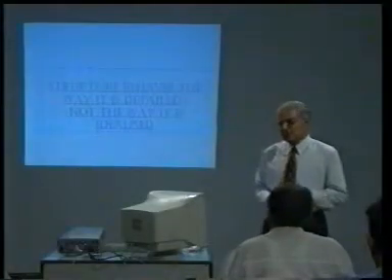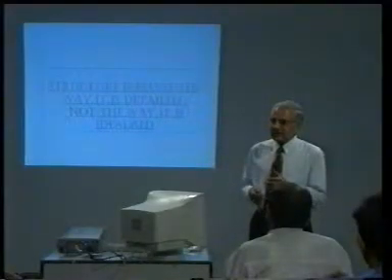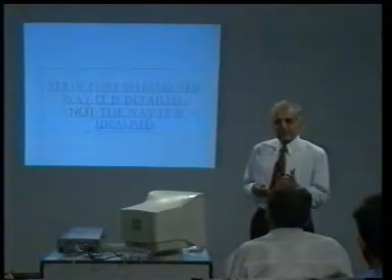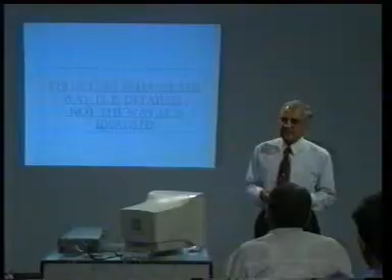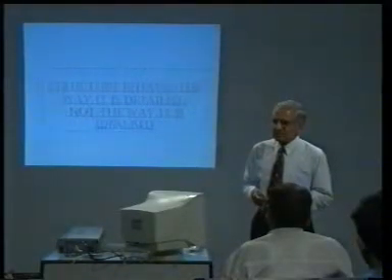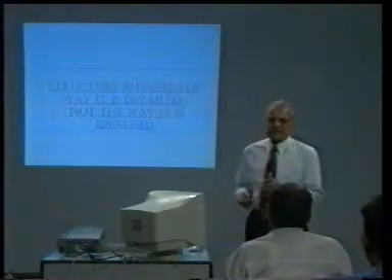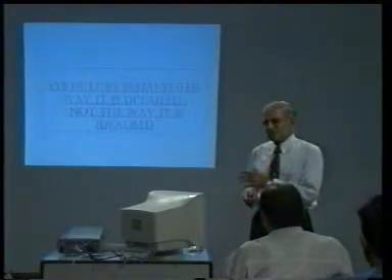Now, before we go on to discuss each of those aspects that I have just listed, we must understand that the structure behaves the way it is detailed and not the way it is idealized. You may plan to have a simply supported condition at the support, but you may actually be providing the reinforcement of the column and the beam to go into each other. This condition actually will be a fixed condition and not a simply supported condition. So, these aspects I shall explain as I go by, but this is a very important aspect, that you must not go wrong in idealizing something and providing something else on the ground.